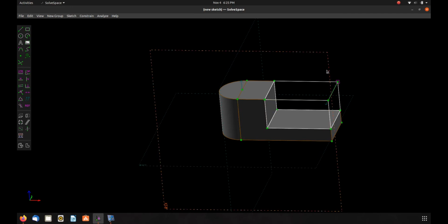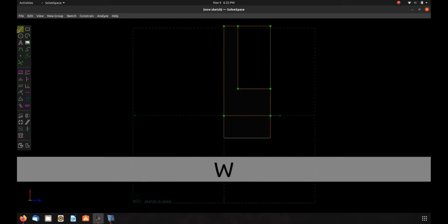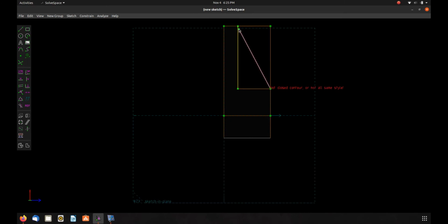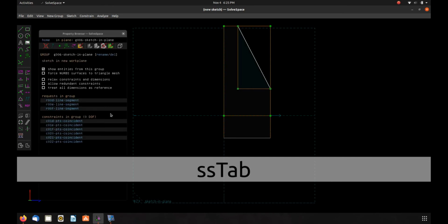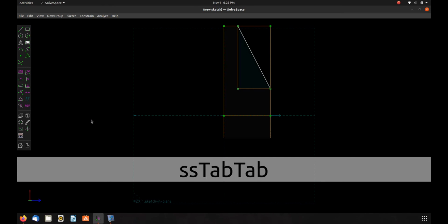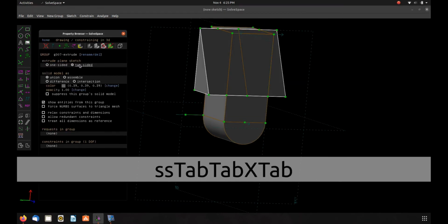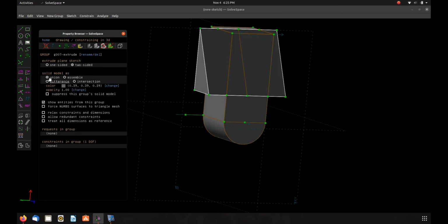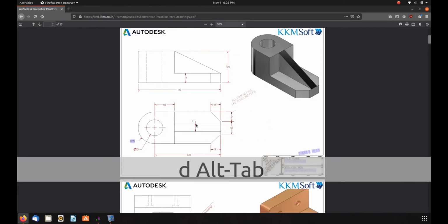Now, I set this up so this sketch, or that plane, I'm sorry, was originally in the middle of this body, for this specific reason. So you can press S and get a line segment. Connect those all together. And that's already fully constrained. So now we'll go ahead and extrude. Make sure to click two-sided. We want to make sure that it's a union, and we'll dimension this to 7 millimeters.